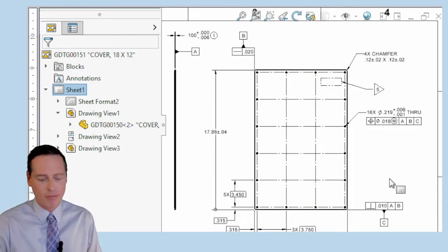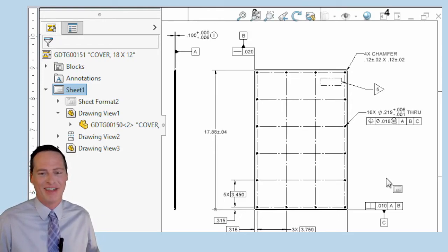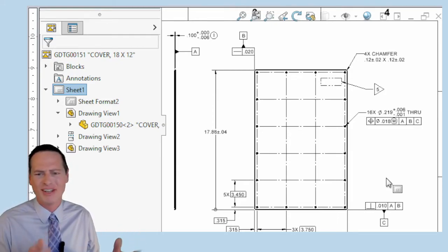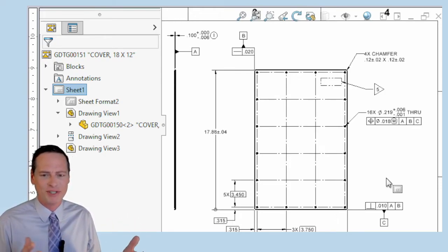And when I go into the assembly and drop it down on top of the frame, I'm not using one edge over another. There's probably no assembly instruction that's going to say to do that. So why these edges in particular? It seems like it could cause problems. Minor problems maybe, the part will still fit probably, but maybe the pattern of holes is shifted too much to one side or another because the part's not being manufactured on center.